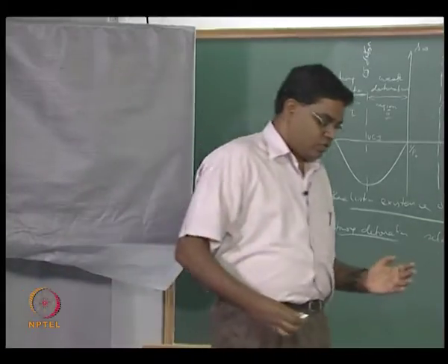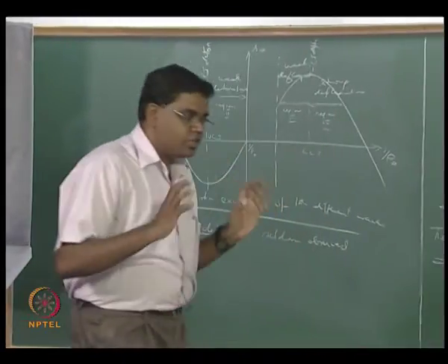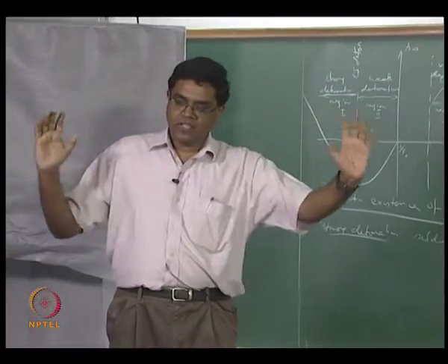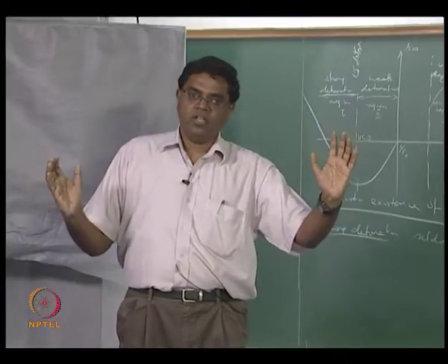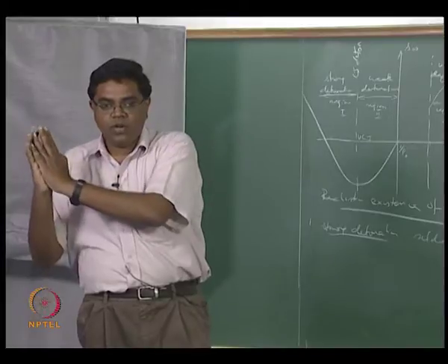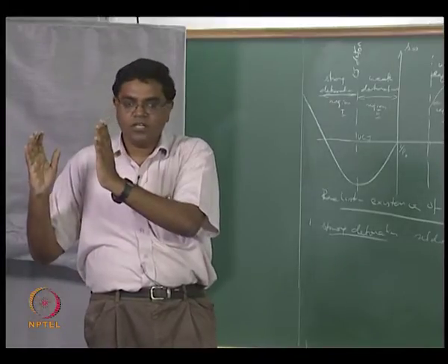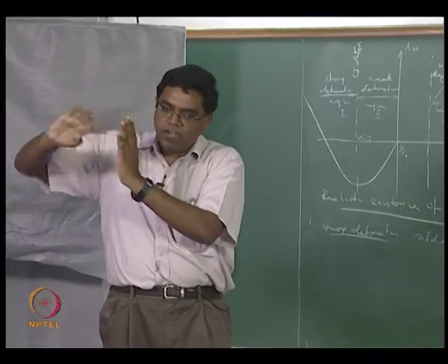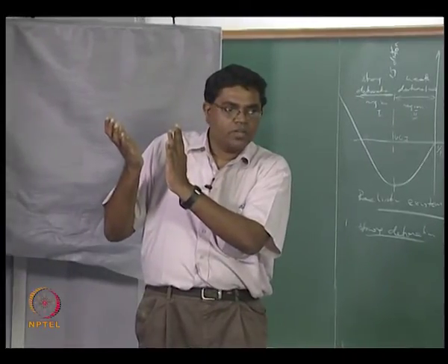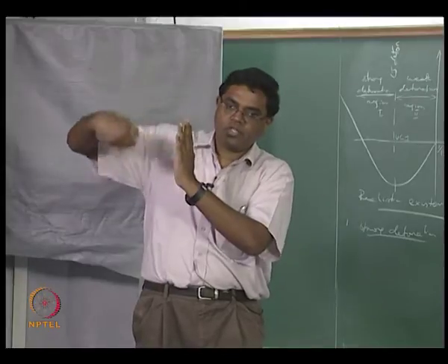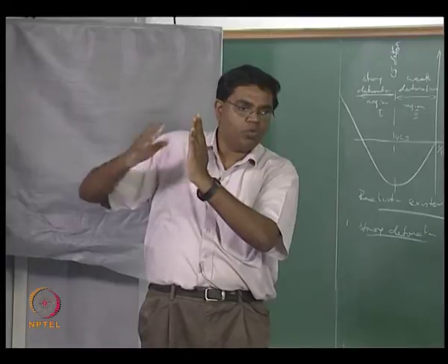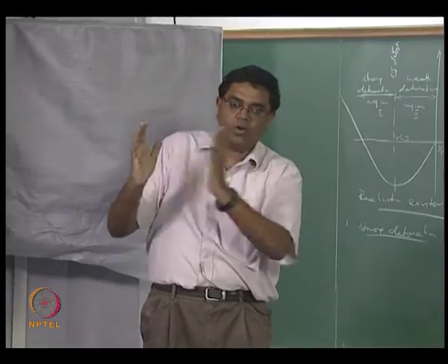Okay, so invariably the way detonations typically happen is if you now have a reactant gas in a confined region and they got ignited at the confined end, and you now have a wave that is beginning to propagate, you now have a confined region where the pressure can build up and stay, right. And once you can have this pressure build up, then you have a transition to detonation wave for what you're igniting, and you now have a detonation wave.